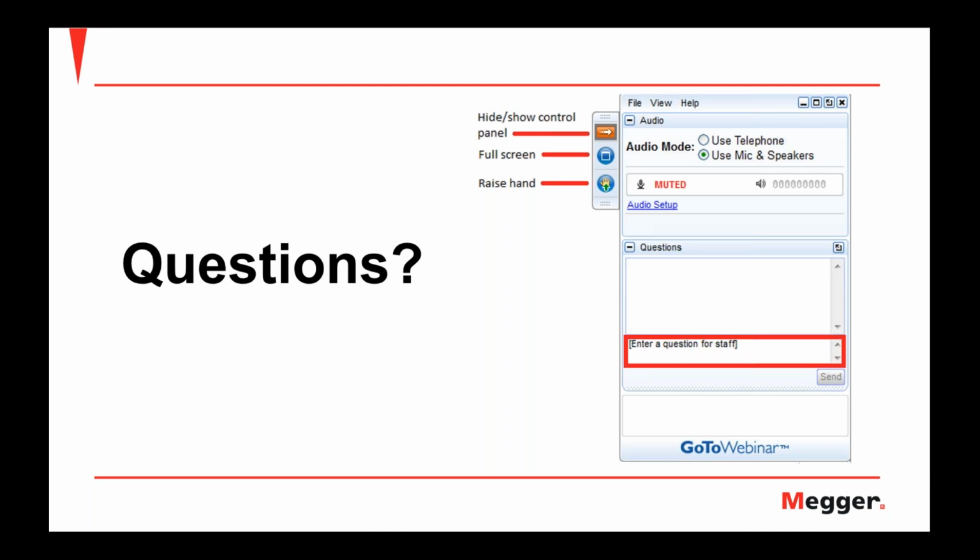Okay, let's see if we can get through a couple more. During operation of nickel cadmium batteries, can we infer something through impedance testing? That's a really good question. Yes, you can, but it cannot be your only methodology of testing. Now, a NiCad battery, because of its chemistry, has a completely different discharge profile. Its voltage and impedance will remain pretty well solid until near end of capacity, at which time the voltage drops off very quickly and the impedance goes up very high.